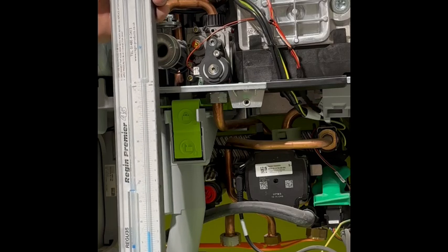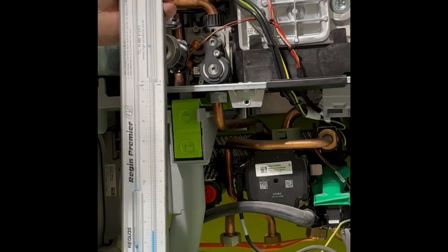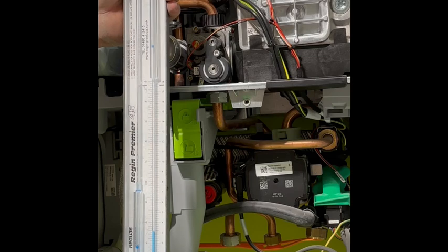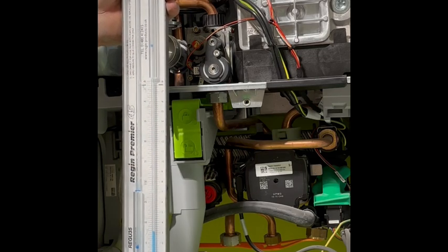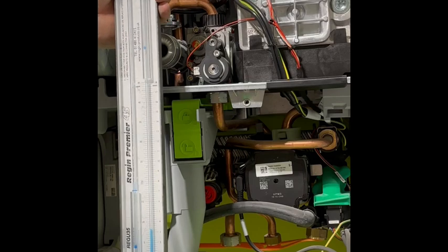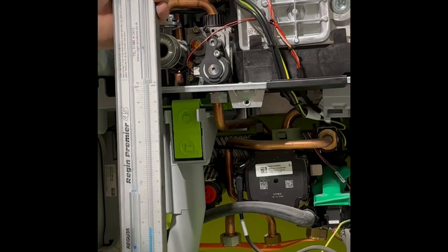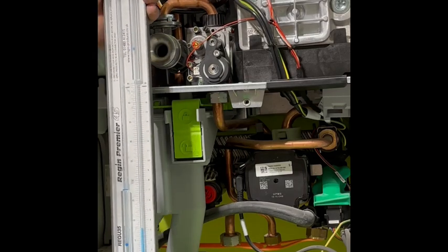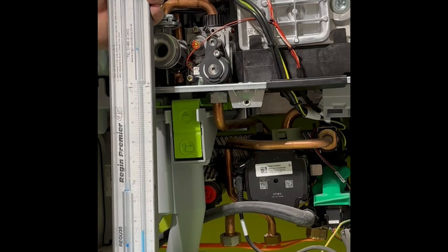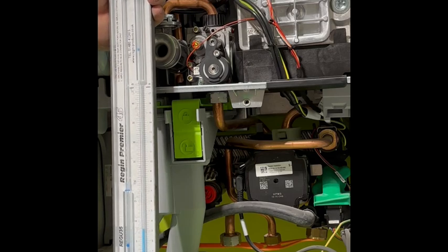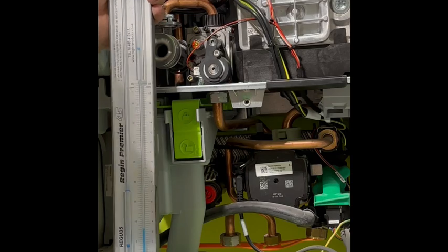20 millibar. Very rare you get that in today's installations. Obviously we've got condensing boilers going on there, which need a lot of gas to start with. People don't upgrade gas supplies, so you find the inlet working pressure to the boiler can be quite low sometimes. Obviously, if you check the manufacturer's instructions, you'll have a minimum working pressure at that appliance.